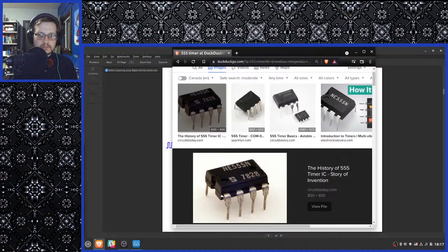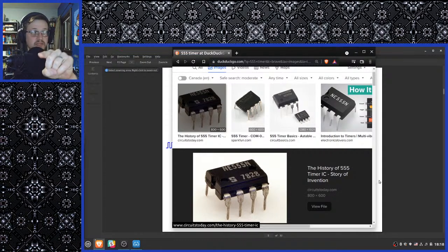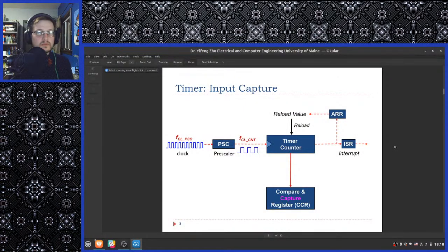This is what we're talking about right here, right? One of these. This thing has a register inside of it, and it also has the circuitry to increment that register inside of it. It does not need to pass any data into the ALU in order to increment that register, because the register is not in the memory, it's not in the CPU, it's in the peripheral itself.